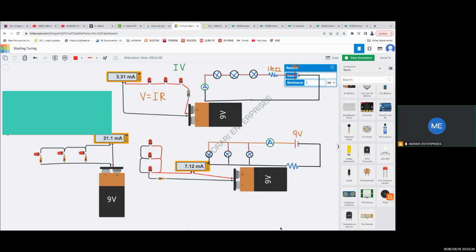So in this case, we connect the light bulbs in parallel. So we call this in parallel, you see. This one is in series, you see, straight current goes here, the same current goes through, the same current goes through. But here, the current leaves here, goes through the ammeter. We can measure the total current in the system first. And then we see here the 7.12. In this case, where we have these light bulbs in parallel, we have more current in the circuit than in this case. Is this also 1 kilo ohms? Let's check this and see that it is the same, 1 kilo ohms.